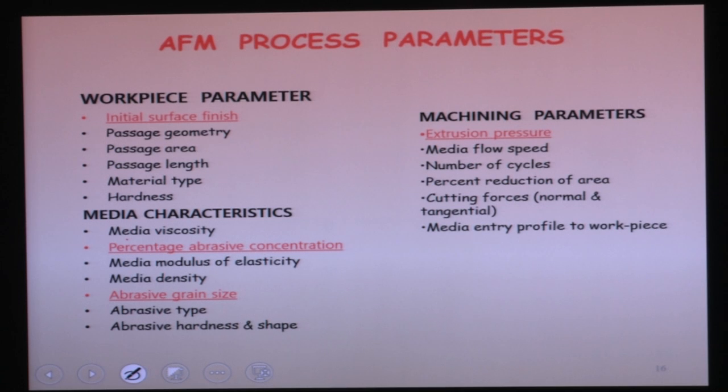Media characteristics, like medium viscosity. The viscosity of the polishing media is the main thing. For different hardness of the workpiece material, you have to change the rheological properties of the media. By changing the rheological properties of the media, that is, by changing its viscosity, you can polish different workpieces with different hardness.